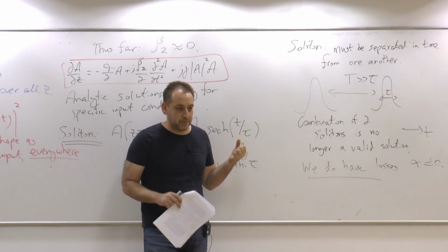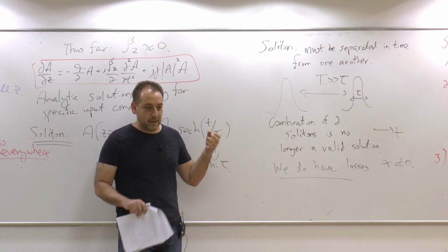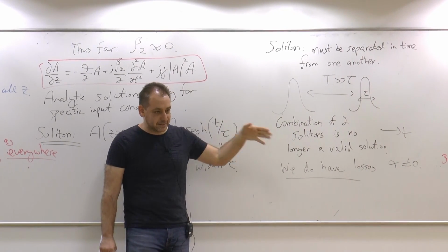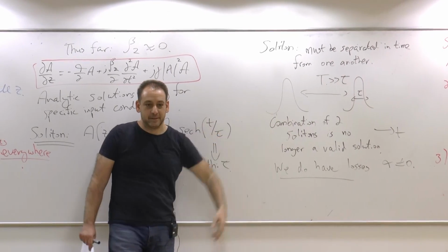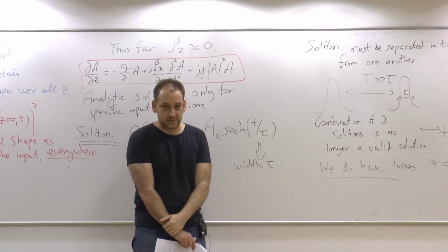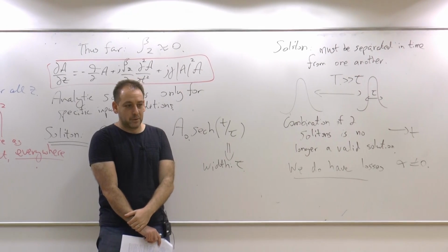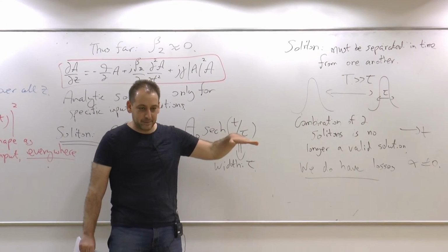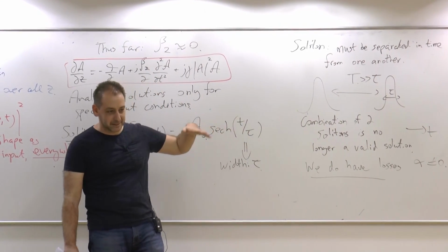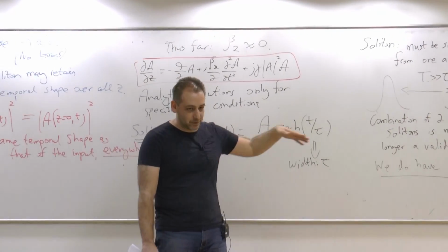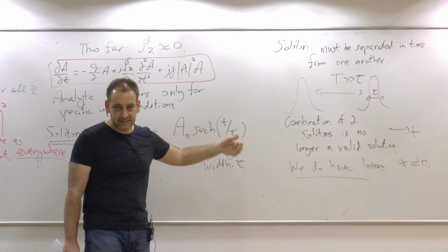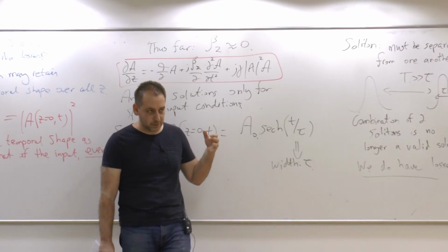And then people came up with an even more clever way to amplify very gradually and smoothly as you go along. If, say, a fiber is losing 5% per kilometer of power, we'll come up with a very gentle amplifier that gives back the 5% per kilometer, and this can be done in a distributed, continuous way using Raman scattering processes that I will address shortly.